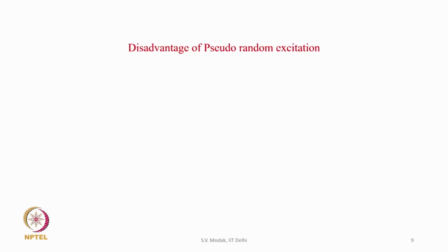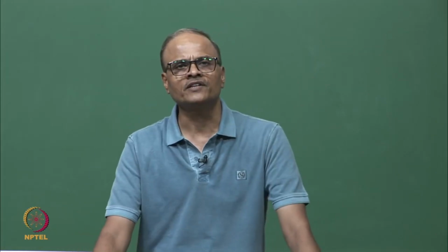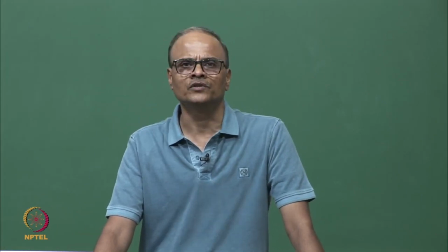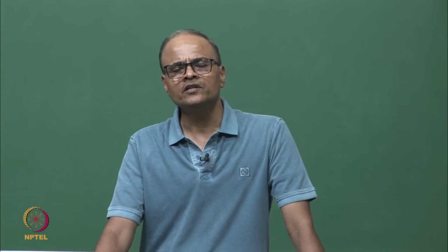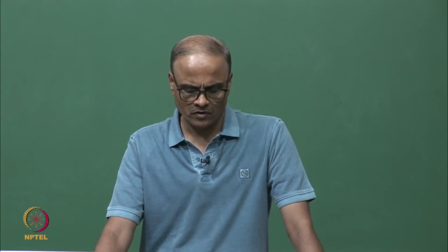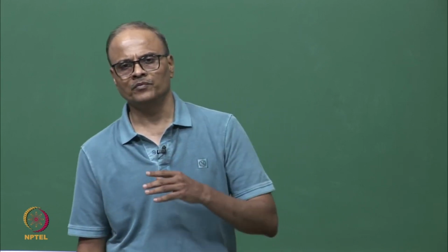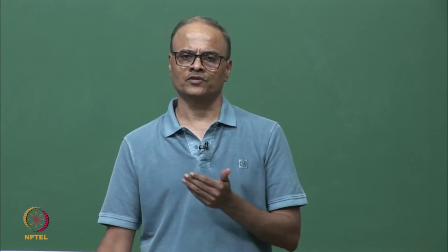So, are there any disadvantages of pseudo random excitation? We see that pseudo random excitation has one disadvantage: if there are any nonlinearities, then it does not yield an FRF corresponding to a linear approximation of the structure.